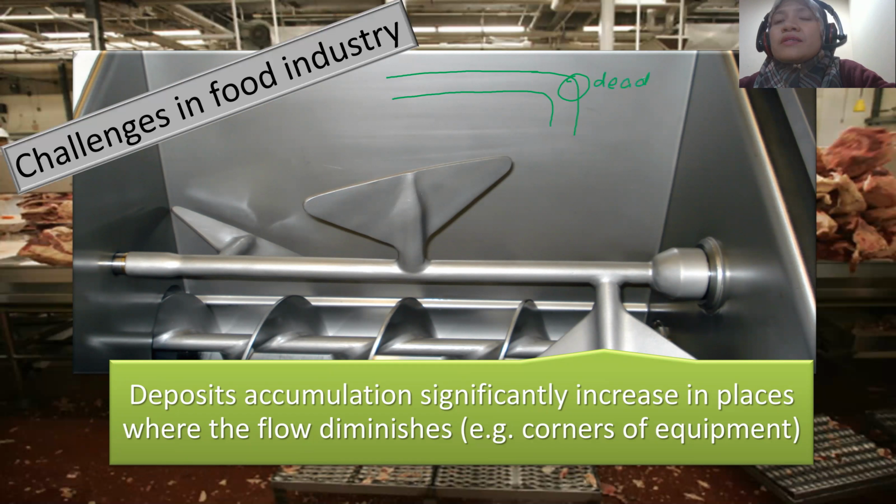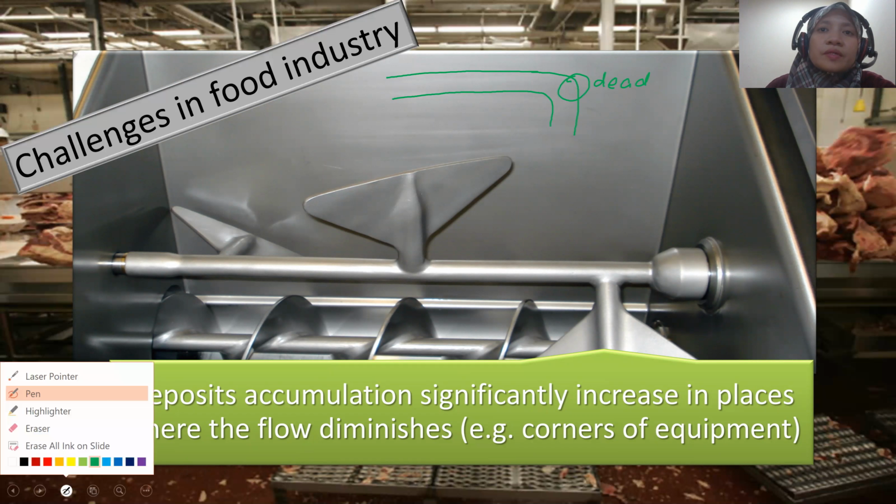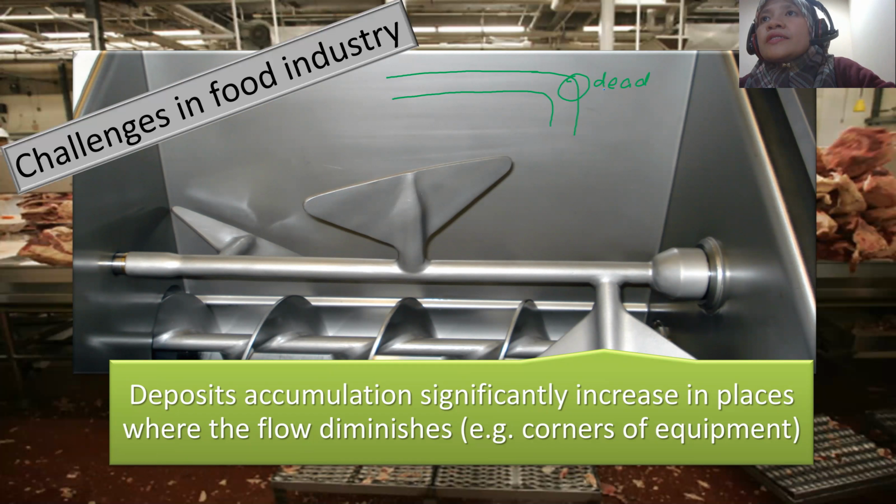Okay, I think I should change the ink color. Okay, it's called as dead zone. Okay, where it will be a nice place for the food salts to accumulate around this area, as the flow, the velocity at this area will be lower than the velocity at the middle of the pipe.